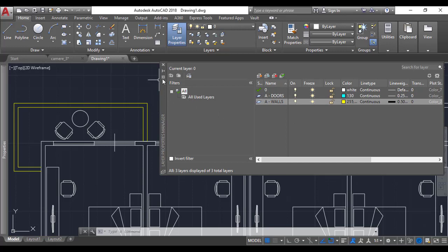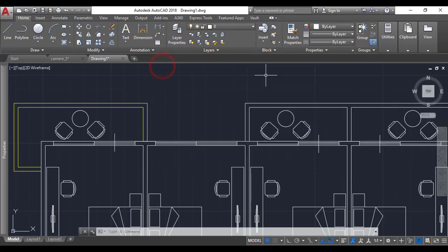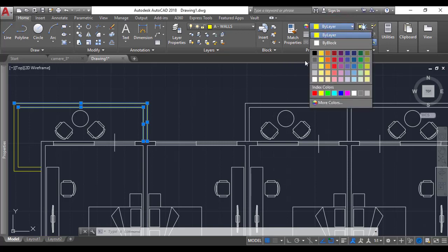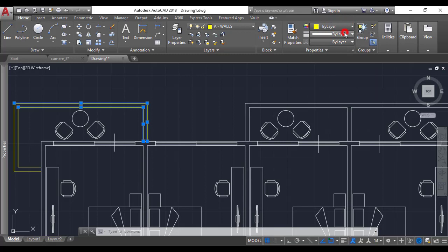All right, so we had a look over there, and then we can also change some of the properties on this panel. If we select our layers, you'll see that this will change. That will also change to the specific layer of the object that we selected. And you can go change the color of the specific layer, and you can change the line weight, as well as your line type. You can still keep it on the specific layer and then change your line types and line thickness.